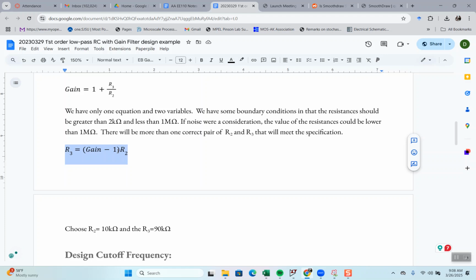Each company does it slightly differently, but it's there. So rather than solve, oh, I want R2 to be 100K and then divide it and might end up with an input resistor smaller than what I want, I do it the other way. A lot of times, 10K, that's just my favorite. You can have favorites too, just as long as they're greater than 10K.